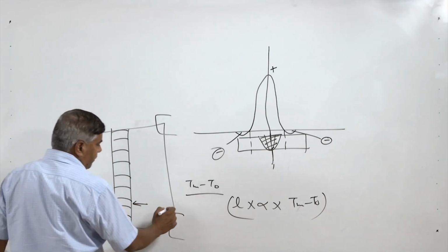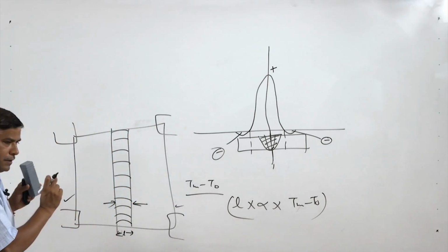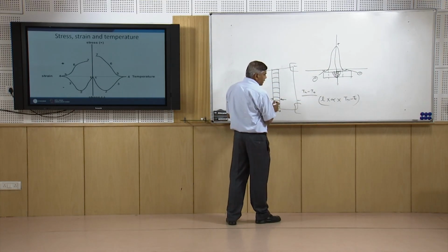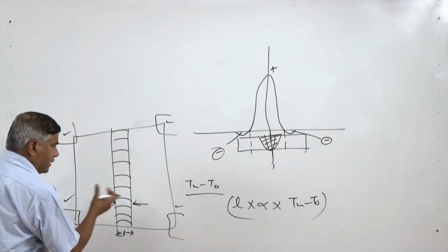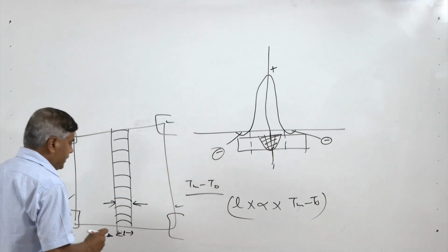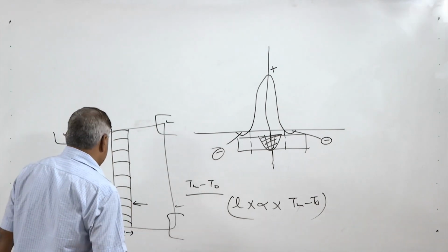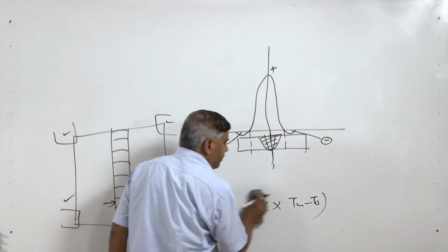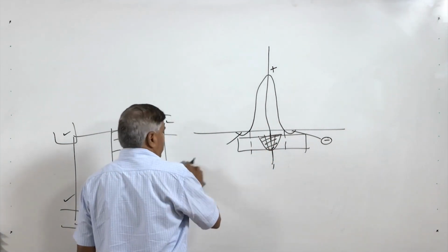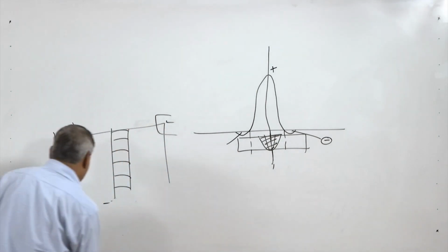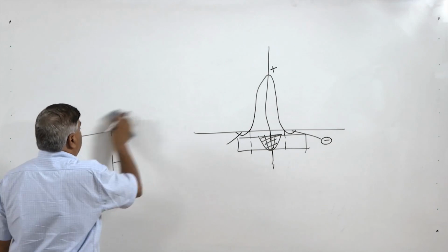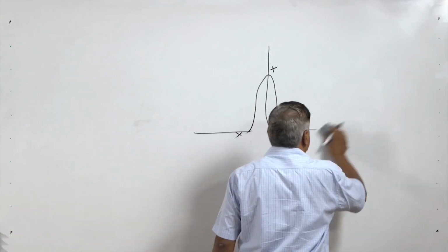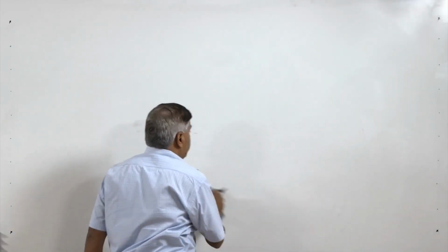So, if the restraints or the plates are held in position firmly, then this transverse shrinkage will be stopped or will not be allowed to happen, and this in turn will lead to the development of, again, tensile stresses in the weld joint. So, this kind of shrinkage, if it is stopped, also causes tensile residual stresses. So, both the residual stresses in the longitudinal direction and the transverse direction need to be seen.